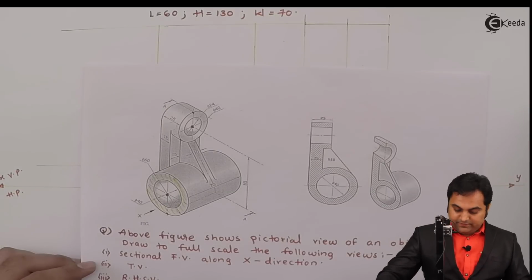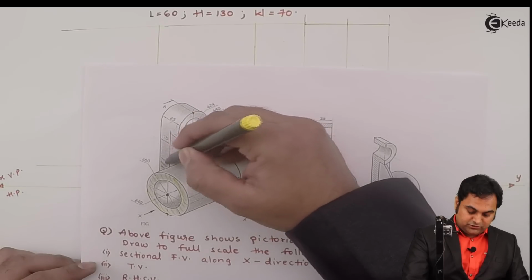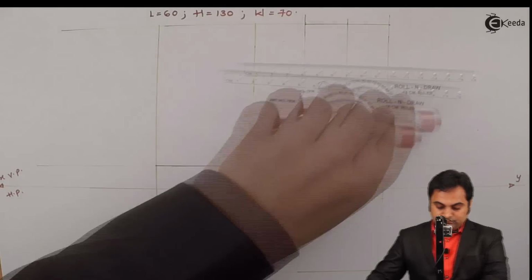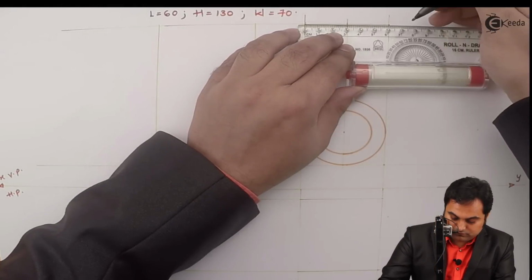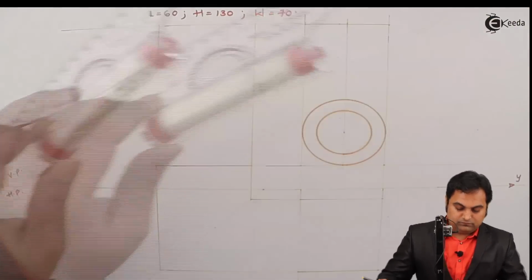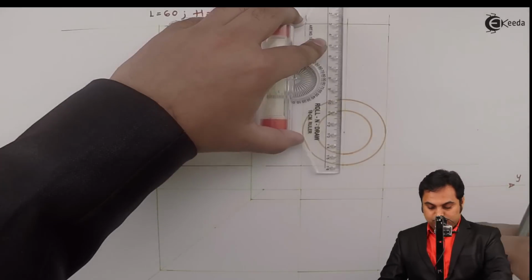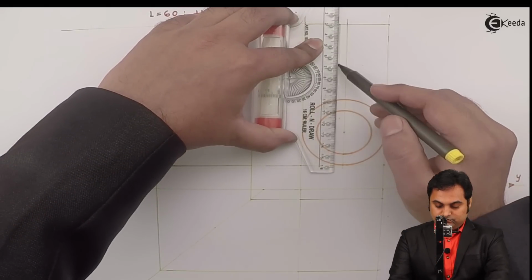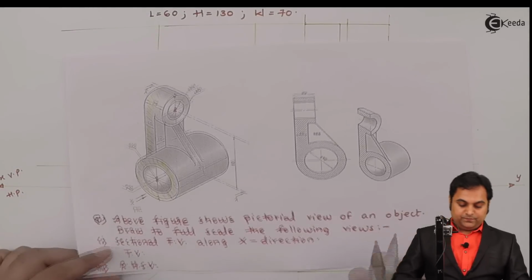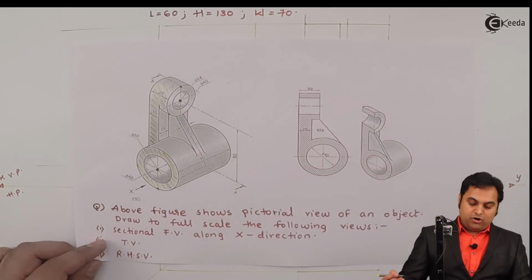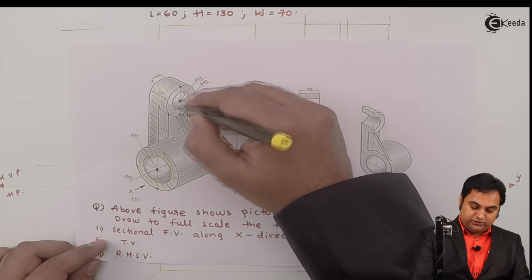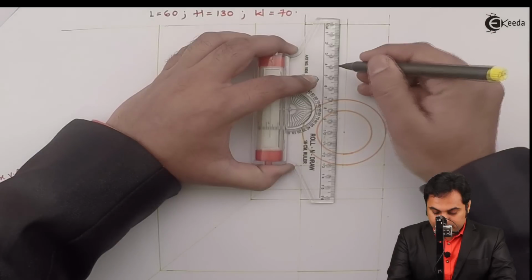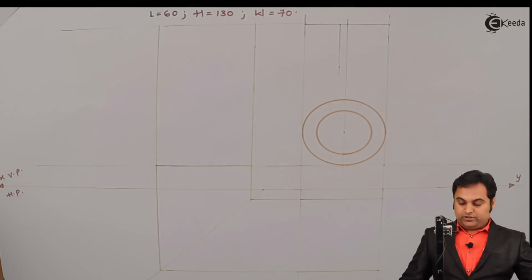Next, here this plate is having 25 mm length at the top, so this surface is also visible from the front view. So taking 25 mm length from the top corner, and projecting a light vertical line, here this surface will be seen as a rectangle of height corresponding to the external diameter, which is 40 mm. So it will go down by 40 mm. Next, drawing horizontal light line through it.